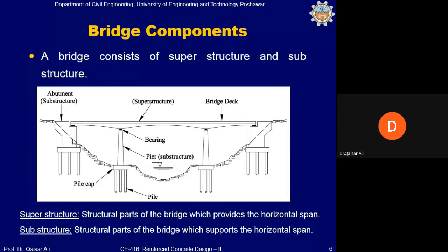Usually this is one of the types of retaining walls, but the typical retaining wall only supports the lateral pressure from the soil, while this type of retaining wall will not only support lateral load from the soil but will also support the gravity load of the bridge coming from the dead load as well as from the live load or vehicular load.